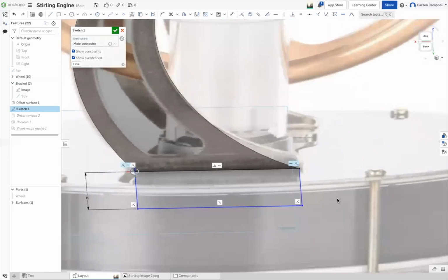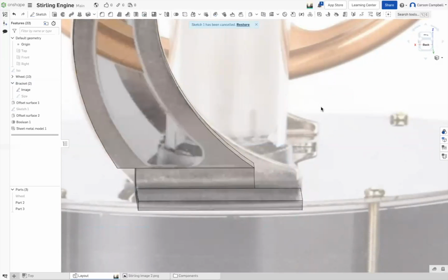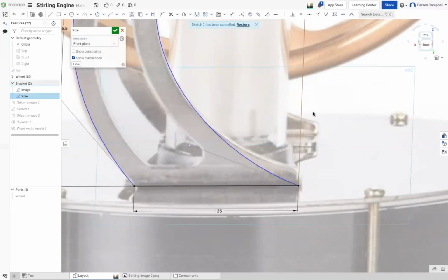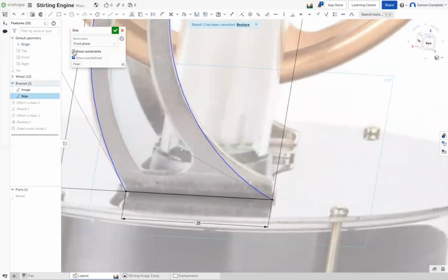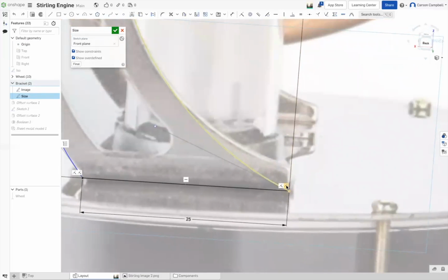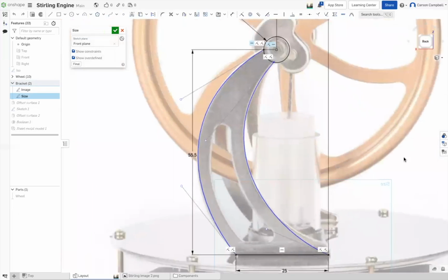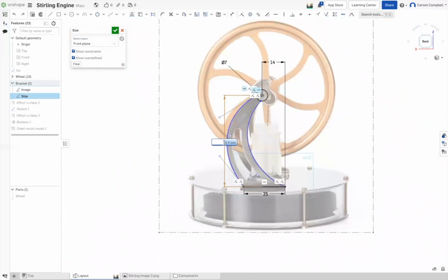And, oh, hold on, we're in the wrong sketch. Yeah, exit out of this. Go to size, yeah, and edit that. Okay, those are them. So, oh, cool. All you need to do is just change your dimension and drive it up so that it's upward. So go hit the N key on your keyboard. This is going to be easier than I thought. Change 55.5 and hit the minus key on your keyboard.